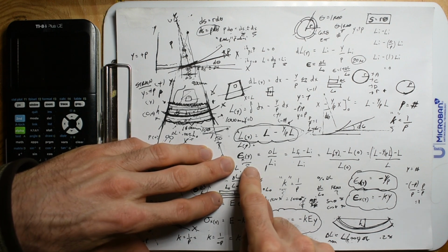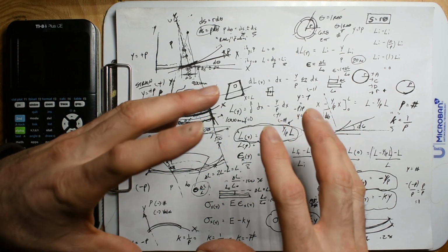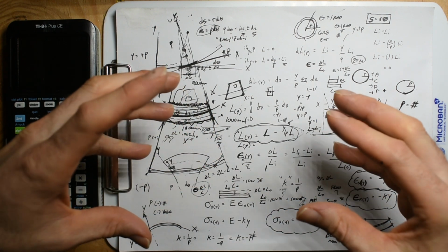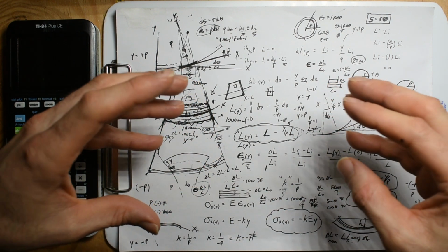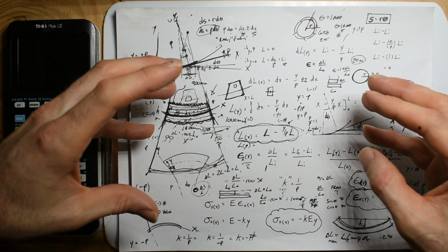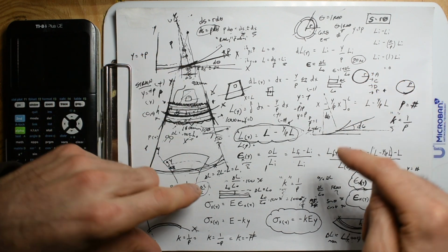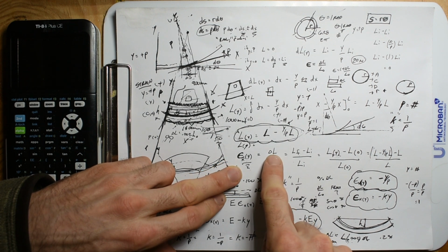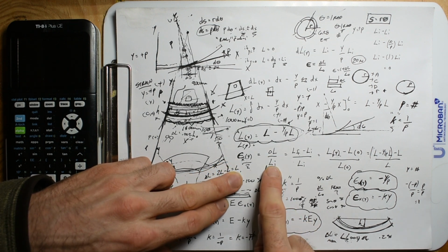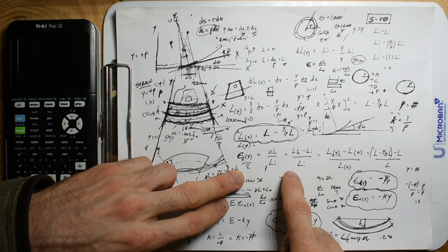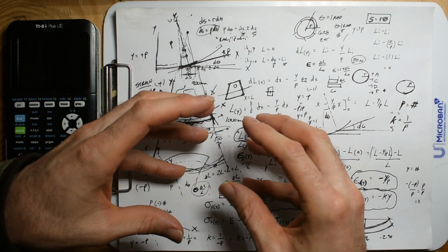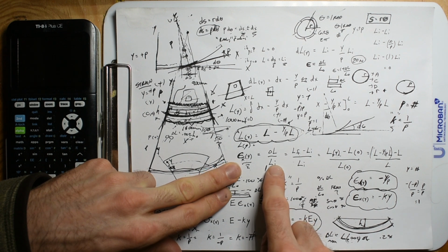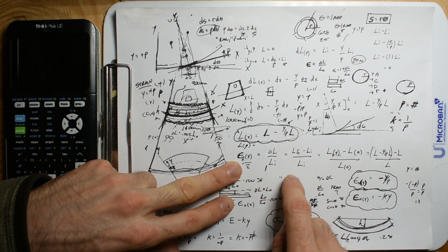That is the bizarre thing, because for steel, the max strain you can have is 0.002. I said if I have 1,000 millimeters, I can stretch it a max of 2 millimeters. Going back to this equation, I changed its length by 2 millimeters. Its initial length was 1,000, so that's a value of 0.002. If I said I could stretch it only 1 millimeter, that would be a change in length of 1, initial length 1,000, so that's 0.001.